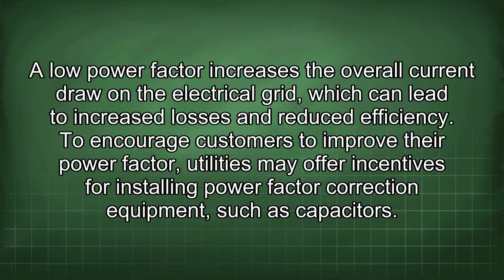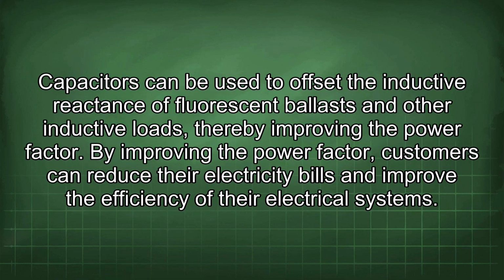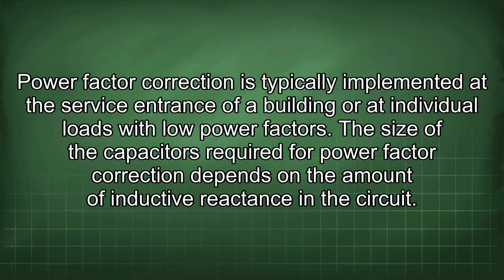such as capacitors. Capacitors can be used to offset the inductive reactance of fluorescent ballasts and other inductive loads, thereby improving the power factor. By improving the power factor, customers can reduce their electricity bills and improve the efficiency of their electrical systems. Power factor correction is typically implemented at the service entrance of a building or at individual loads